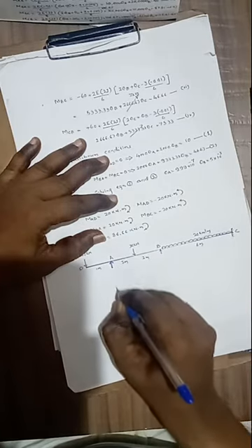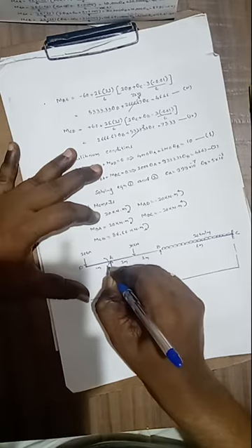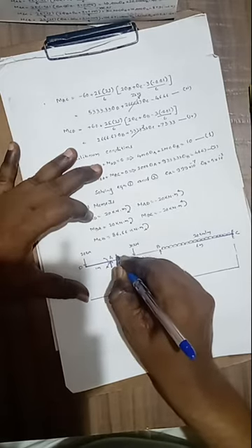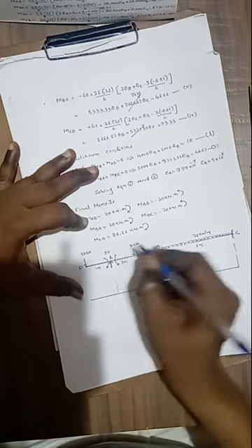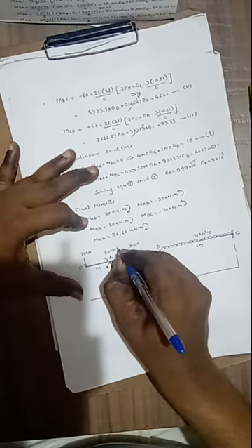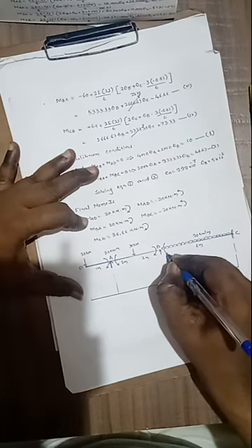Here, by extending these lines, now we can draw the bending moment diagram for this one. This one is the datum line. Here we can mark these ordinates. By observing these moments, here MAD is clockwise, that is positive or clockwise moment, and MAB is anti-clockwise. This one is 20 kilonewton meter. Similarly, MBA and MBC are of the same magnitude.